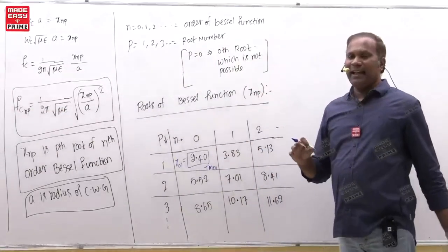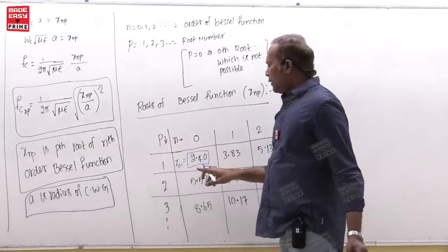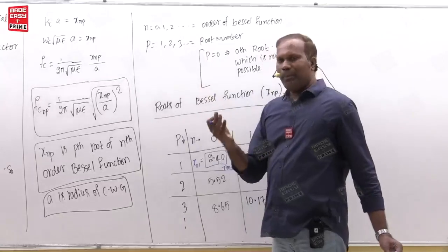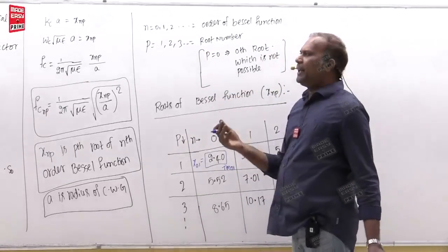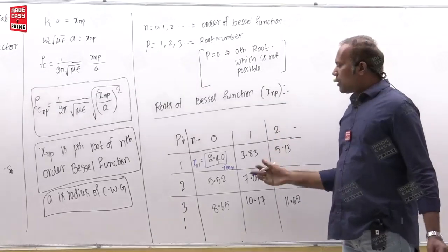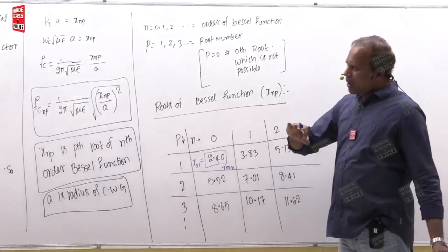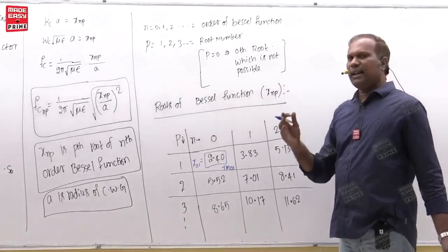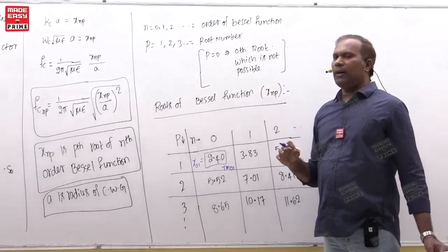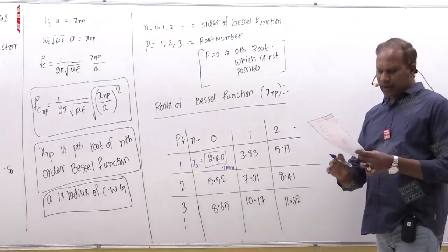But have you seen in TE modes, in place of 2.4, we got 1.84. So you can make 3 statements. Among TE modes, TE11 is the dominant mode. Among TM modes, TM01 is the dominant mode. In a circular waveguide, among all the modes, TE as well as TM, the least cutoff frequency is for the TE11 mode. So that is the dominant mode. Anyway, remember this one also, but it is not that important.